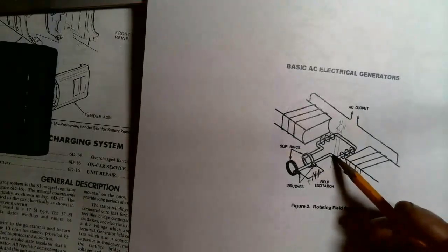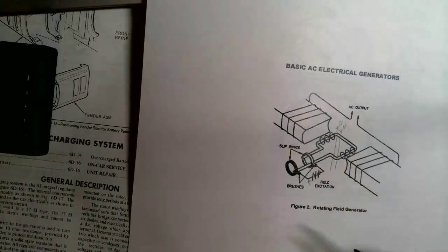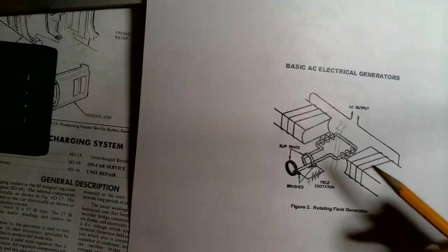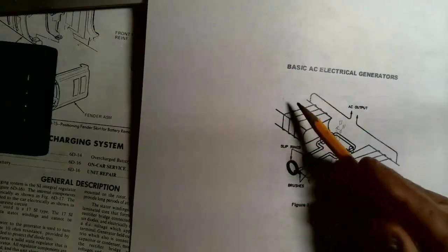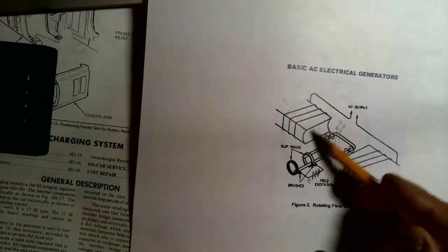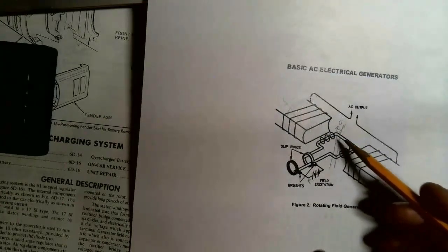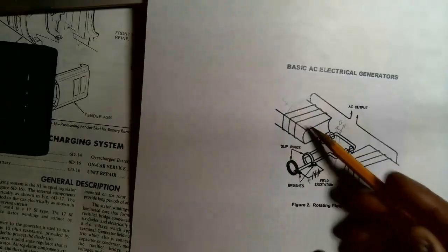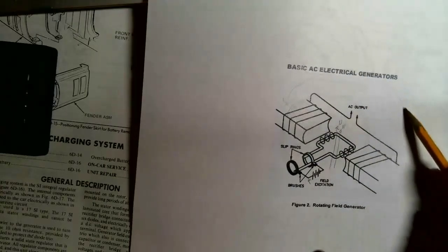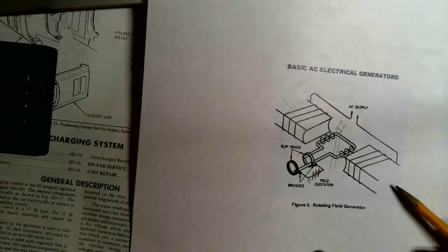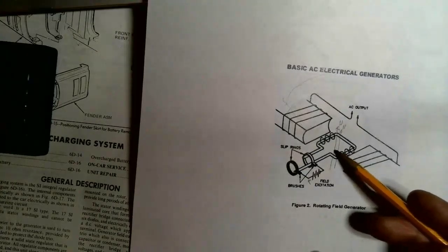Now suppose I rotate this 90 degrees counterclockwise. North would be facing to the left, and I would have magnetic flux coupling through this coil, and through some kind of magnetic material here, presumably iron, that's a good magnetic flux conductor. The magnetic flux flows through here, coupling all three of these turns, then flows through the frame of the stator, back around to this side, couples through these three coils, and back through the rotor again.